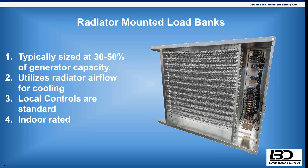Moving on to our radiator mounted overview. Radiator mounted units, it seems like 26% of you are seeing these less often than the stationary load banks. There is a time and a place for both styles of units. A radiator mounted unit is typically sized at 30 to 50% of the generator capacity, and is designed as a supplemental load, in comparison to the stationary that you can go to 100%.